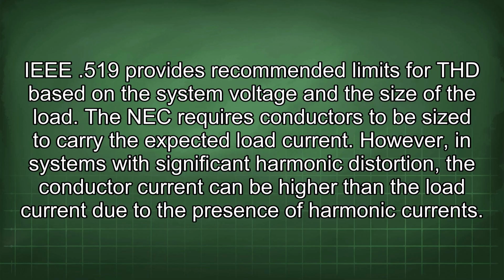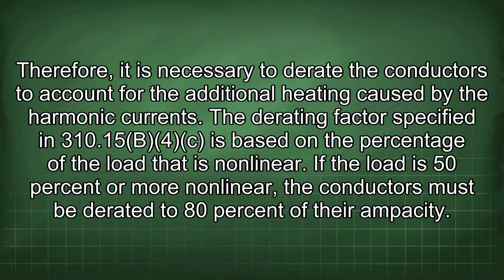The NEC requires conductors to be sized to carry the expected load current. However, in systems with significant harmonic distortion, the conductor current can be higher than the load current due to the presence of harmonic currents. Therefore, it is necessary to derate the conductors to account for the additional heating caused by the harmonic currents.